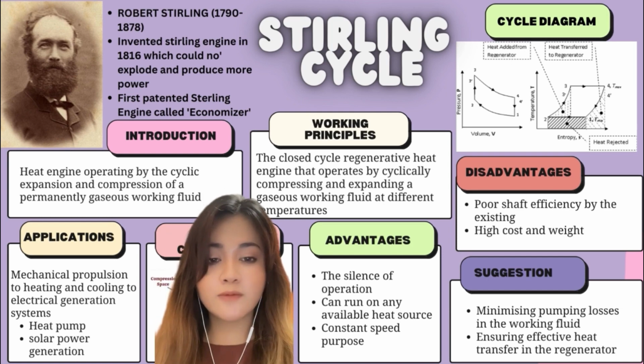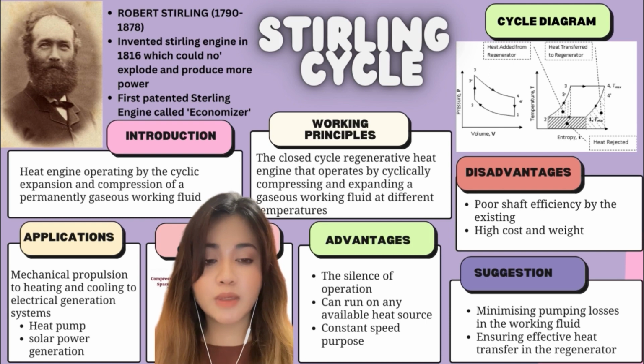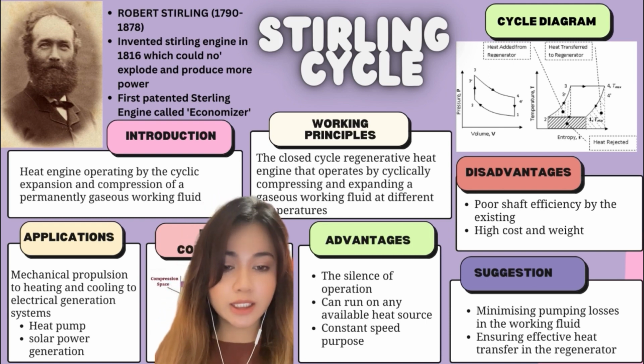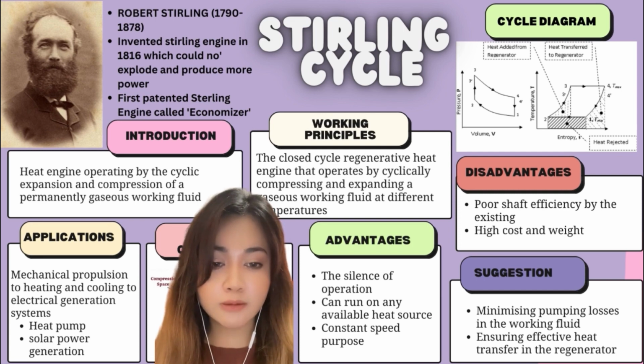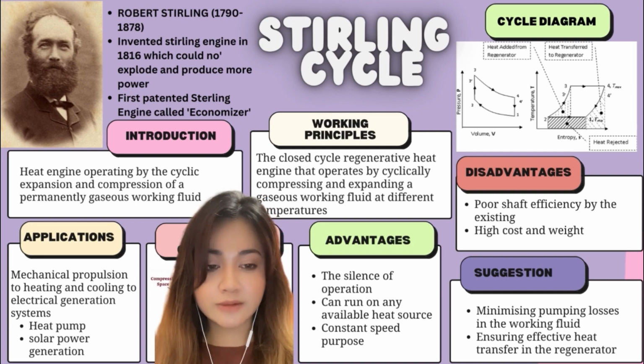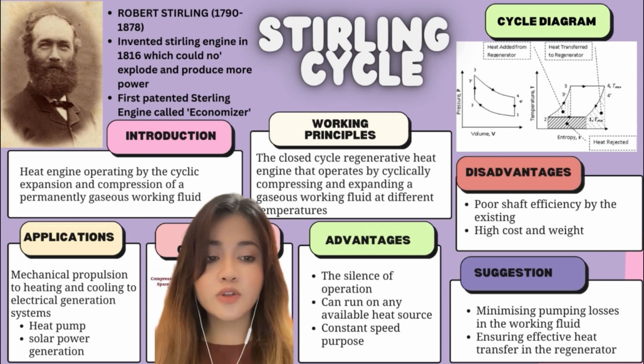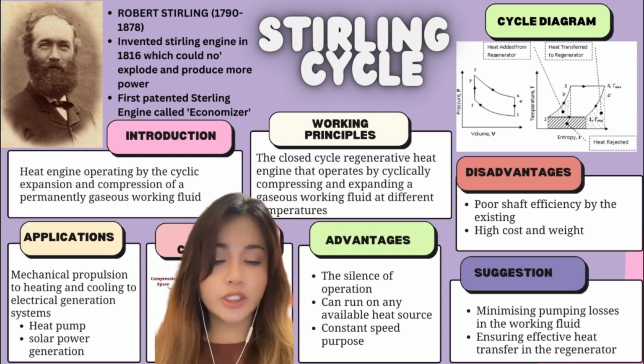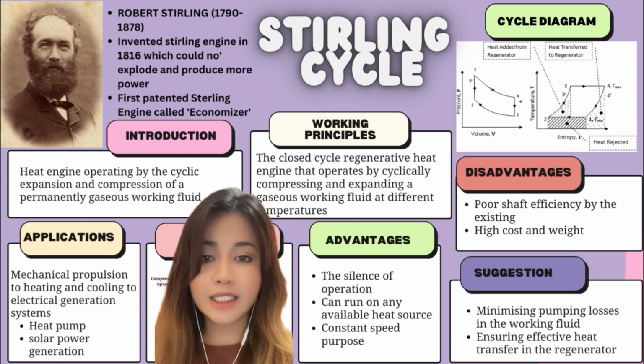My suggestion for this cycle is to minimize pumping losses in the working fluid and ensure effective heat transfer in the regenerator. Keep the maximum temperature difference between the hot and cold end of the engine.